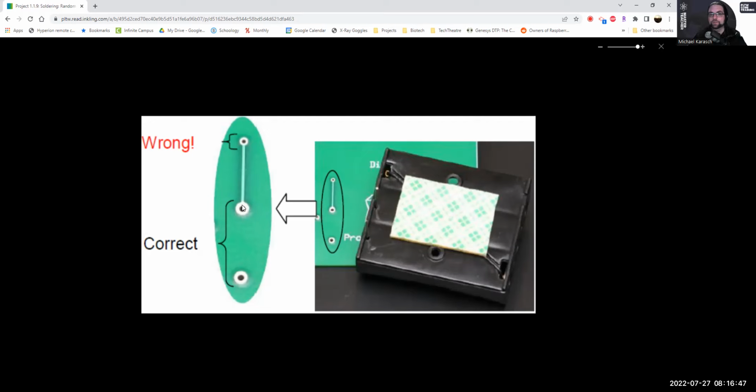A short circuit has a really low resistance and voltage remains constant. We talked about this with Ohm's law. So if resistance goes down, current goes up. Okay. And batteries have a lot of current capability. And the other thing that comes with lots of current is heat. One of the reasons why short circuits are so very dangerous is because a huge increase in current is a huge increase in heat.